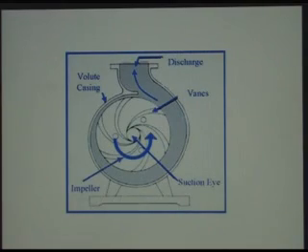So on centrifugal pumps, how does the pump operate? Well, you've got a spinning impeller, and fluid comes in to the center section of the impeller and gets pushed outwards by these vanes that are rotating at a high speed, which imparts velocity to the fluid. Again, using Bernoulli's law, you have a slight drop in the static pressure as the fluid is accelerated, and then it starts to build up static pressure as well as velocity head as it travels out through the impeller. And then out here in the stationary section it is slowed down again to generate the static head from the velocity head that's been imparted by the impeller.